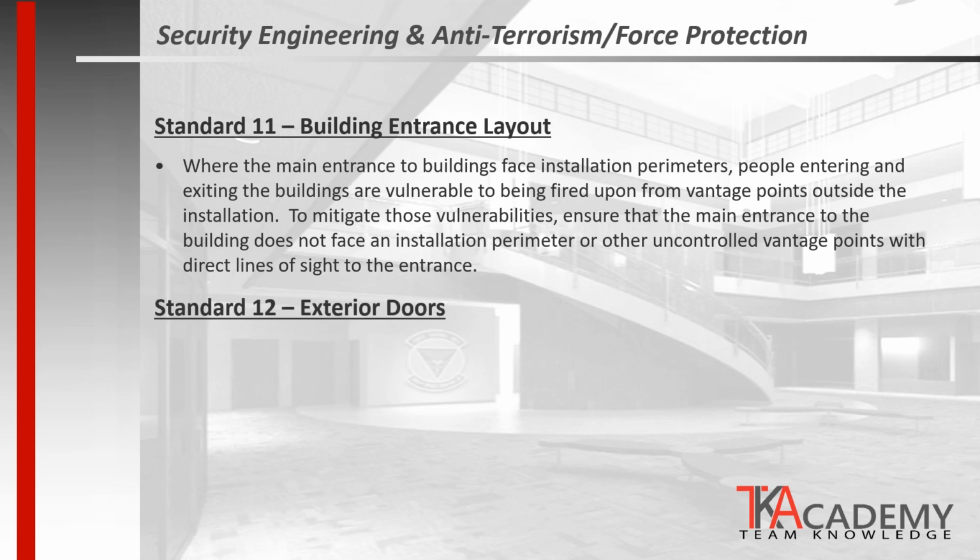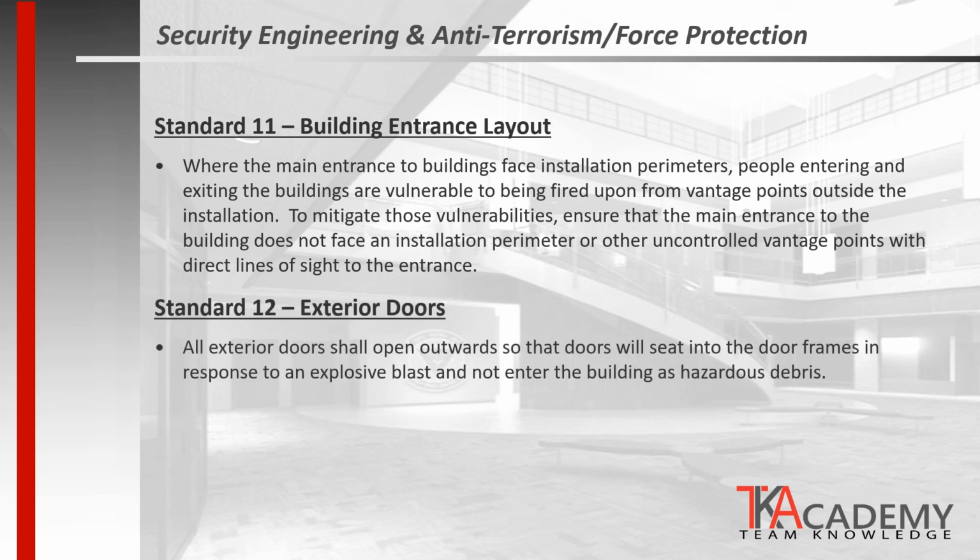Standard 12 for exterior doors states that all exterior doors shall open outward so that the doors will seat into the frame in response to an explosive blast, and they are not thrust into the building as hazardous debris. In most cases, exterior doors will swing outward for egress requirements, and this is typically not an exception to the standard building norm.